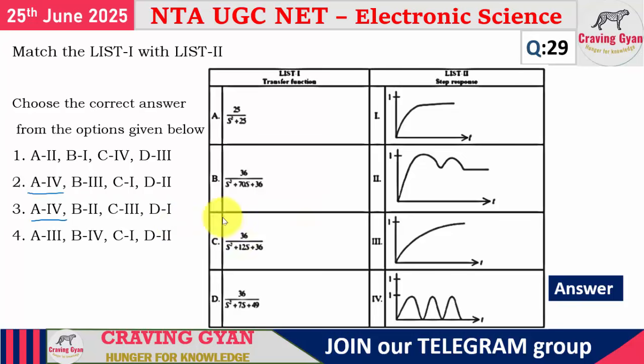Next, let us solve for the third one. So it is 36 divided by S square plus 2 zeta omega n S plus 36. Nothing but omega n square. Omega n, you are going to get as 6. Zeta, you are going to get as 1. Zeta equal to 1 means this option. For C, you are going to get 3. So based on this, option 3 is going to be followed.